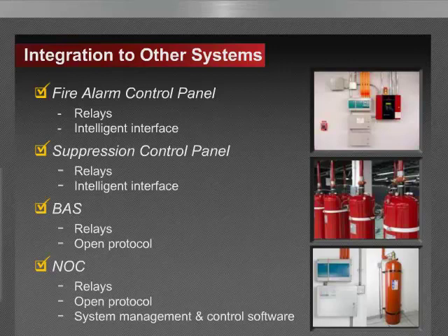Where smaller air handling units are used, I won't say how many because it all depends on the size and capacity of the air handling unit, but it is possible to use a branched configuration in a single pipe to get multiple air handling units. I would say discuss with the manufacturer for very specific application.